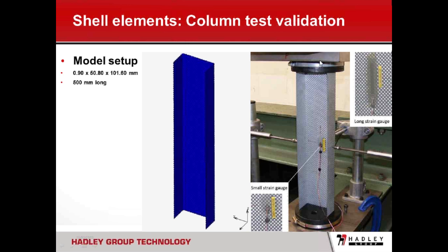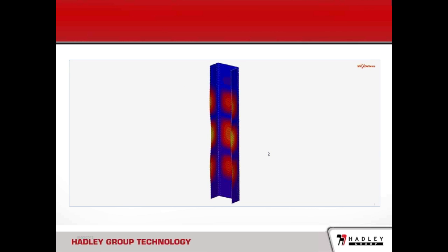As you can see, the load is applied at the top of the column, and under compression load, the column will buckle and fail, and we need to perform the FEA simulation for this mechanical test. And here is the simulation result. You can see the color represents the displacement contour in the analysis, and at the beginning the column buckles first. Here you can see this buckling mode, and after this buckling we apply the load further based on this buckling mode, and then the column will fail.